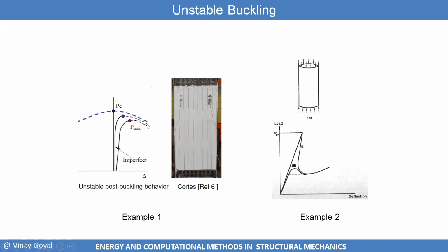So that's a negative stiffness with P delta. P is the load applied, delta is the transverse deflection, or the end shortening. Delta in this case is the end shortening. And what that means is how much it is contracted. You can see here clearly that this is a negative stiffness.